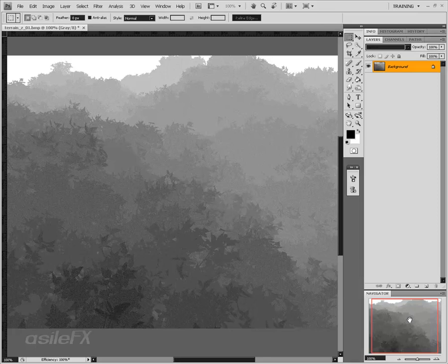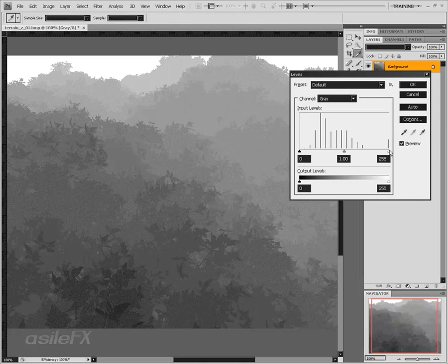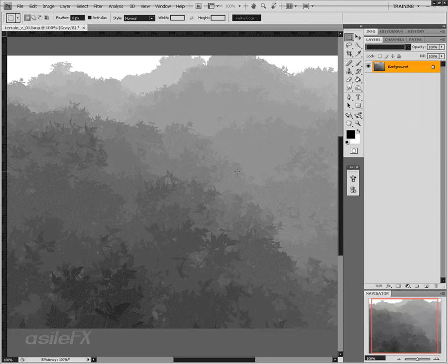Closest to the camera is going to be the darkest, and farther away is going to be white. Now, by restricting and bringing in that lower level, what we've done is reduce the distance between basically the atmosphere and the last point of depth, or the terrain, which in this case wouldn't really matter because we would cut that out with an alpha anyway and have something else behind it. But for the most part, this ZDepth is very troublesome. And because it is automatically saved as an index file, it is also a little more difficult to work with in post.